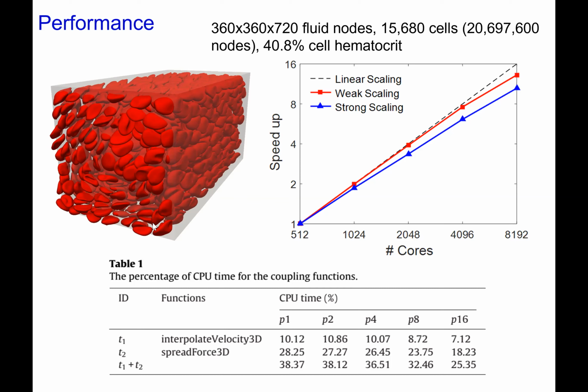But for Palabos, there's no matrix at all. You just need to run the density distribution functions, and then it's jumping around. There's no calculation of the inverse of the matrix to get the solution. So in that sense, it's quite a bit faster. Actually, in one of my classes, I asked the students to compare the finite difference method and the Lattice-Boltzmann method. Lattice-Boltzmann method is way faster. That's why we didn't choose OpenFOAM or FEniCS, because for those methods, you still need to solve the linear system.